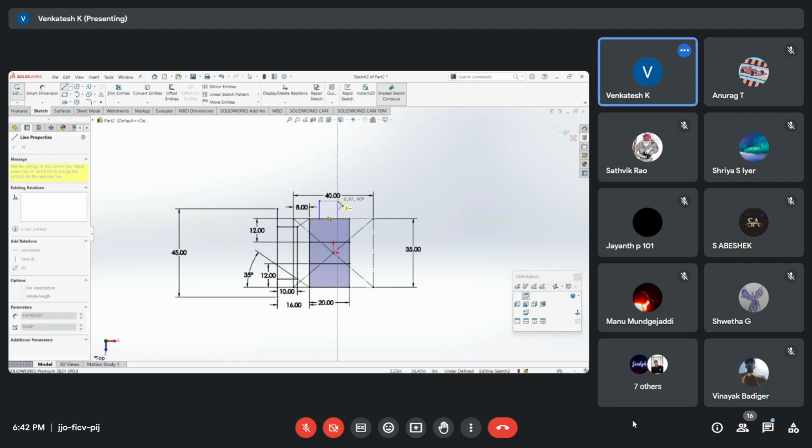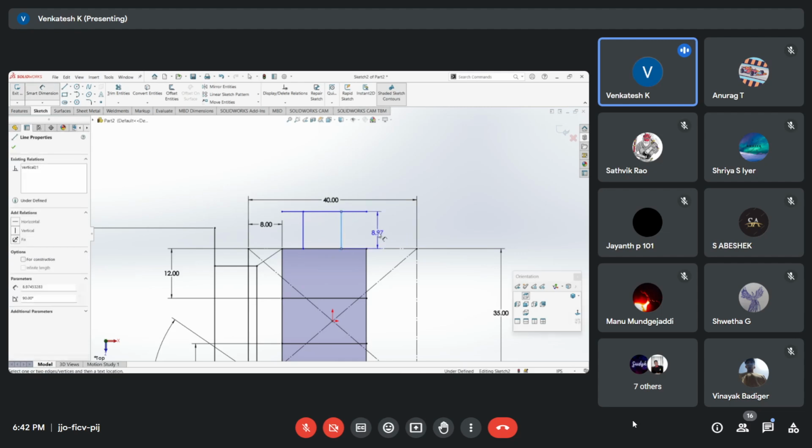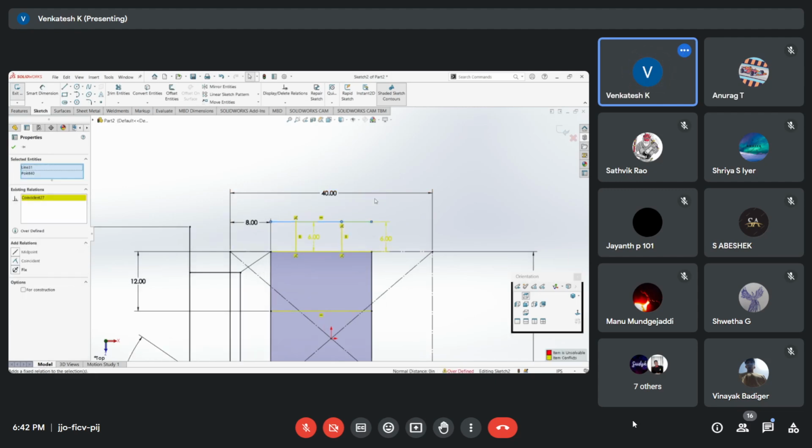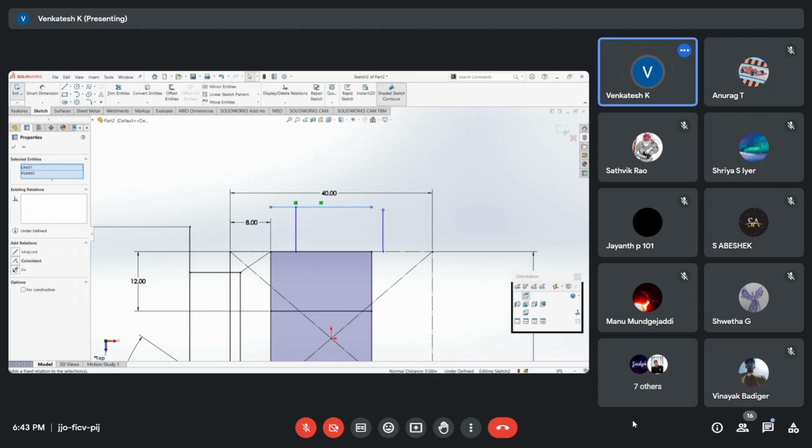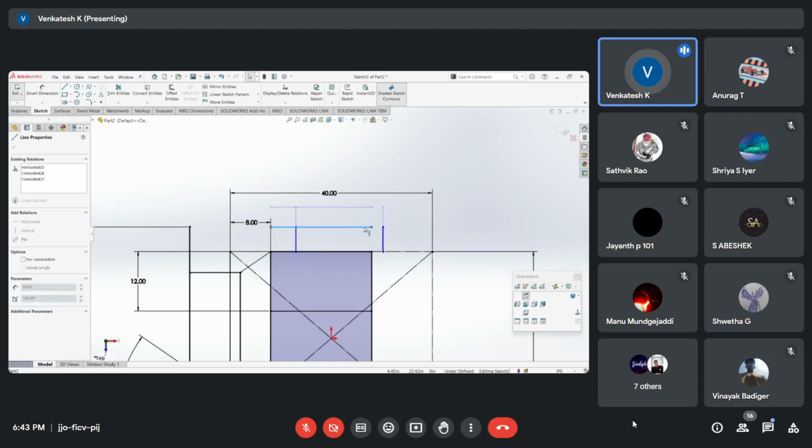Draw two members. Member first. This will be 6. Make sure that these both are coincident. It is coincident, you can just check it. When you drag two things, you'll see this here. Now this is not coincident with the line. Since I can drag this point up and down, to make sure that it is coincident, you need to select both using control and make it coincident. Now it is coincident. Now if you try to move one thing, all three of them move at a time. It means they are coincident.